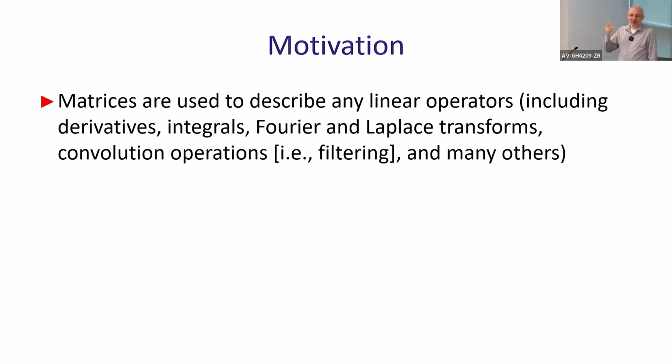You don't need to compute integrals. You don't need to compute anything else. So in discrete space, you're just using matrices for that. You're multiplying by matrix, you get DFT transform. This is how it works. And if you want to find inverse DFT transform, you multiply by inverse matrix, same matrix, obviously, okay? And it gives you inverse DFT transform, which is nice to have, right?